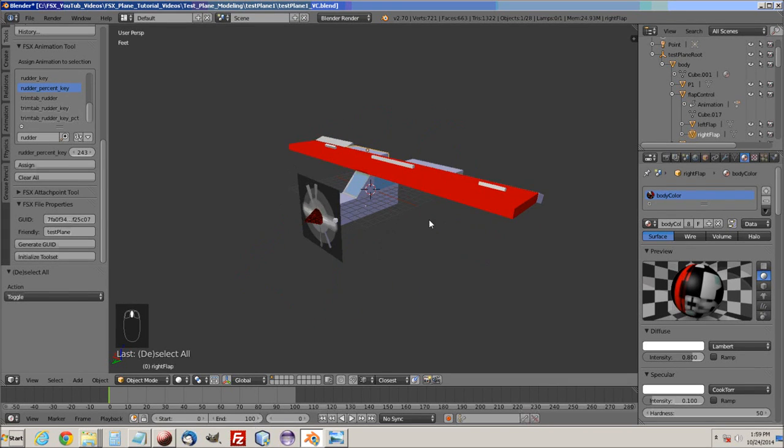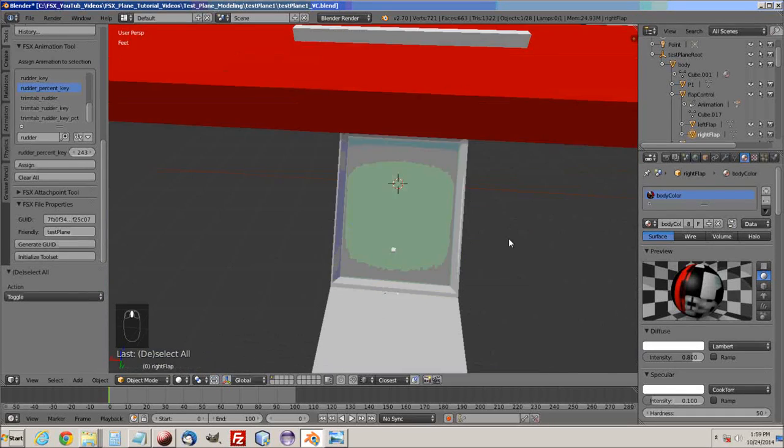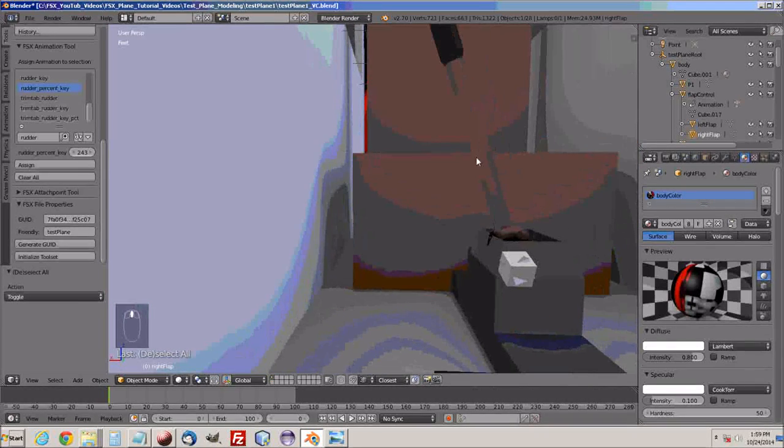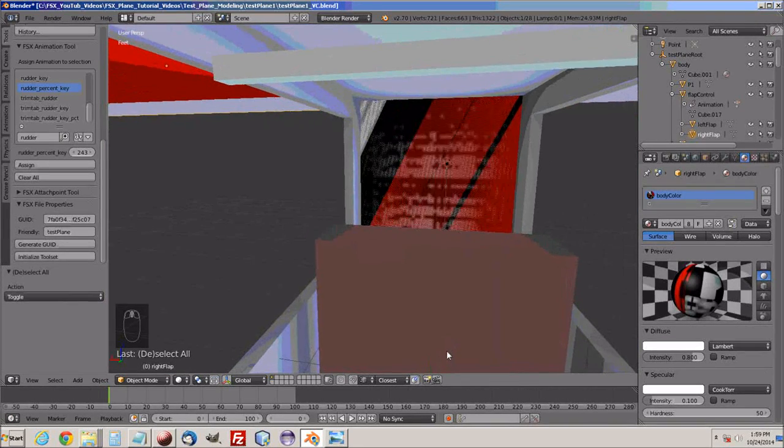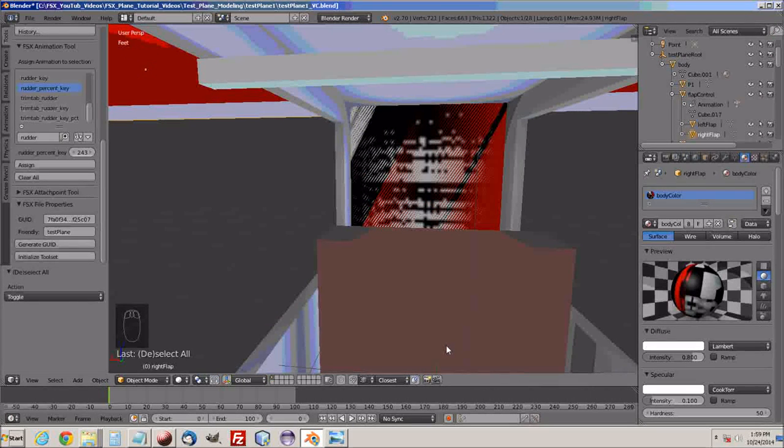Another thing I messed up in the video, if you remember when we UV unwrapped our fuselage, in the UV editor window, we saw some vertices that were out of place with edges that were running across the UV map. The reason for that is I added in this face here so you cannot see through the cockpit, but I did not re-UV unwrap the fuselage mesh. So that's why we're having that problem.